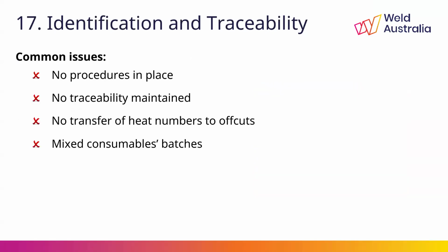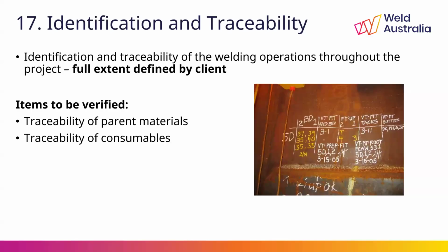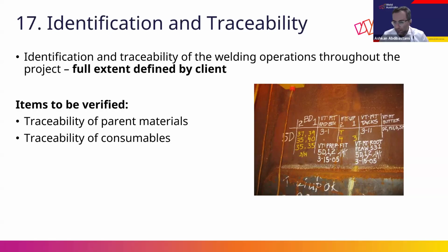Another question, sorry, Ashkan. Calibration and validation of equipment. If the welding machine doesn't show the actual value of parameters, not digital, can the verification of the values be done using a calibrated clamp meter to get the right number? Okay, if the power source doesn't display any value and it has only some selectors to set the value, you can do the validation.